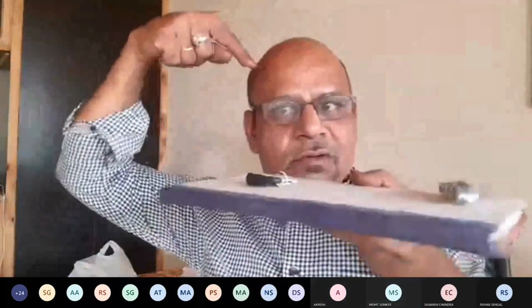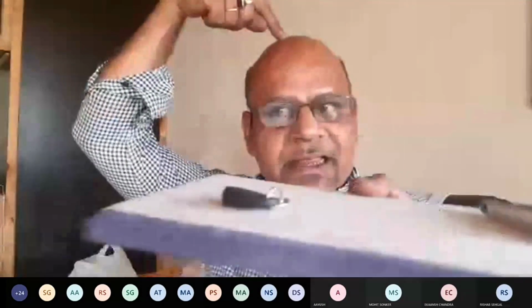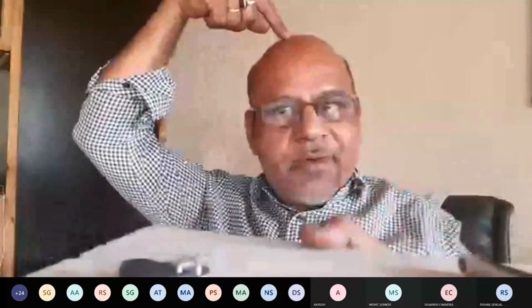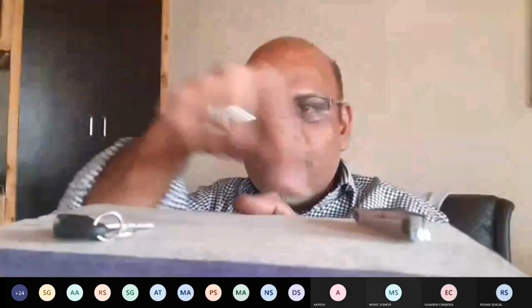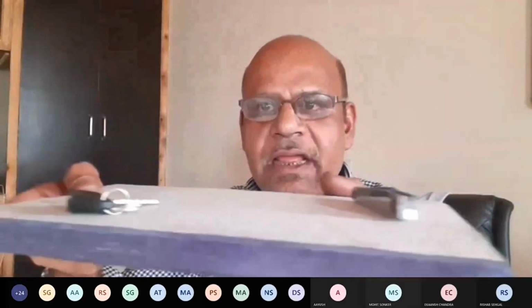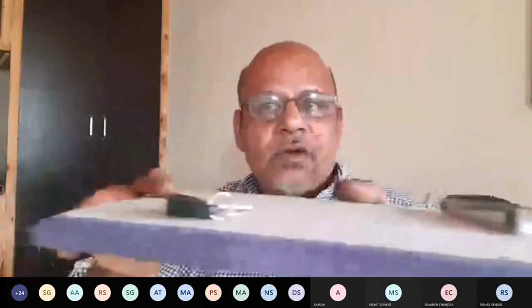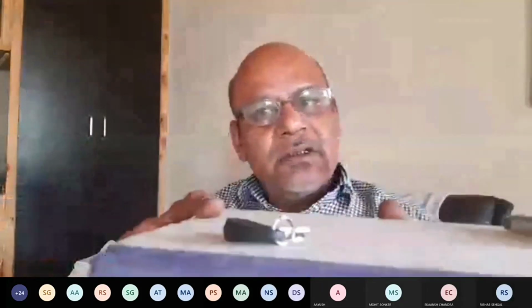So from the ground object, I see they are going to strike the ground. They are going to touch the buoy because they are moving with respect to the buoy like this. But between themselves, the two are not moving. If both are floating, the effect of the current on both is equal, net effect zero. Both are moving, and from the ground I am seeing them move at 2 knots. There is a 2 knot current, and I see both going at 2 knots. They don't collide with each other.